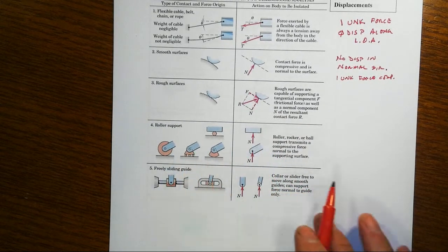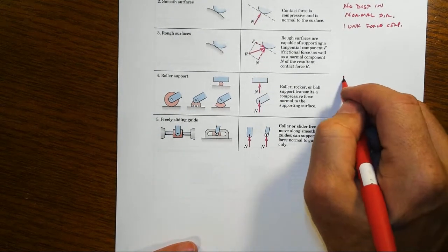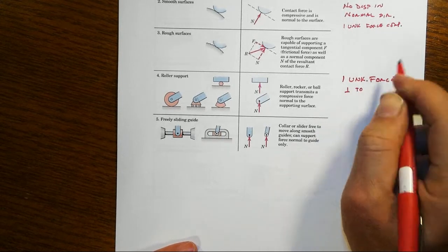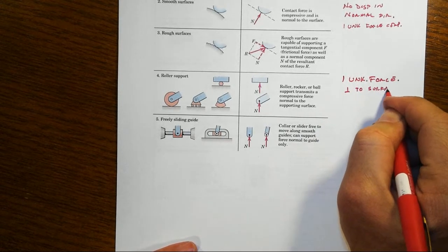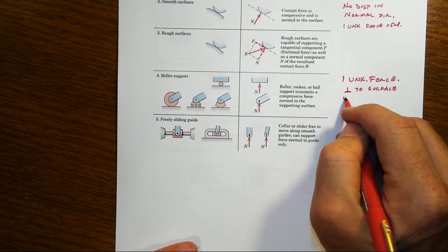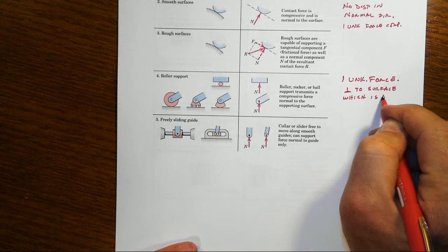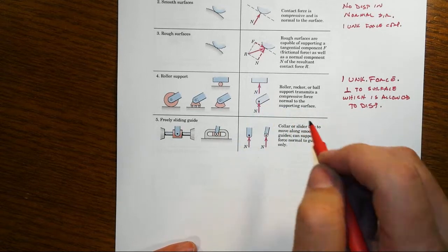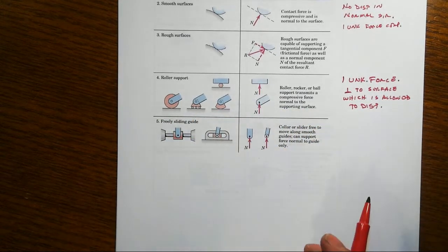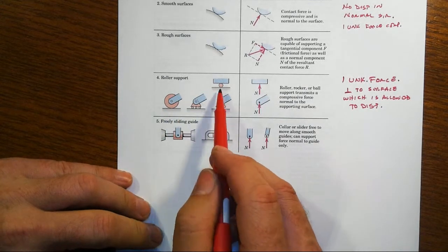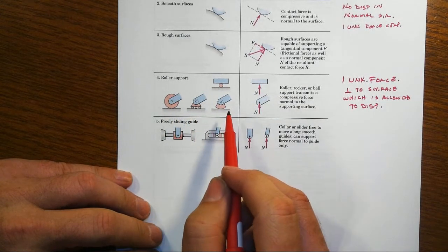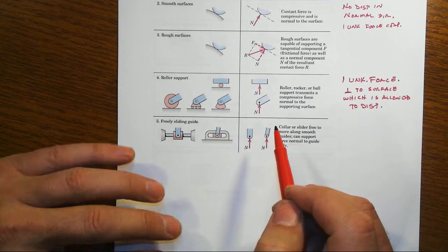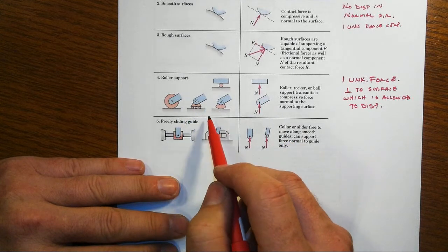Right? The roller support then is a more general kind of situation where we have this one unknown force component that is perpendicular to the surface, which is allowed to displace. Such as what you see here. A lot of times they're on horizontal surfaces. People think, oh, it's a roller support. These are the four common different symbols, and they think that means all roller supports would have a normal force that's vertical. No, not necessarily. It could be inclined.